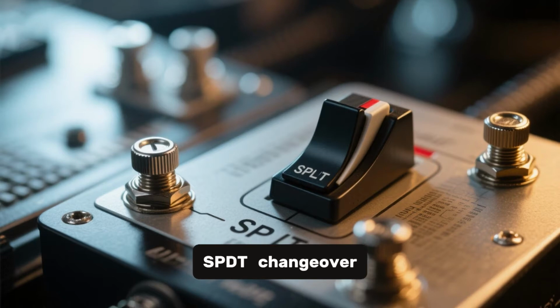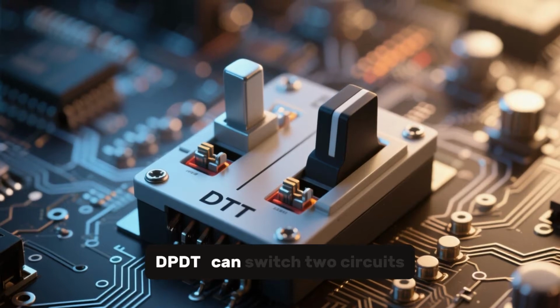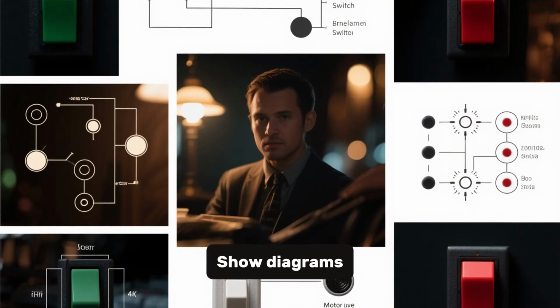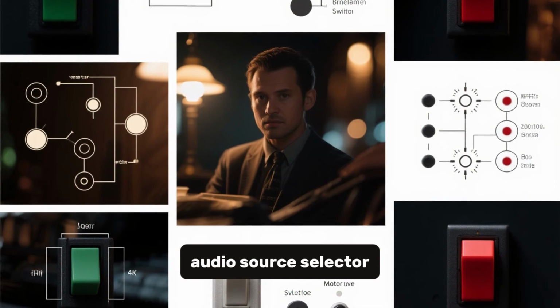SPDT, changeover: one input, two outputs, useful for toggling between circuits. DPDT can switch two circuits or reverse polarity, for example motor direction. Show diagrams: simple wiring examples for each configuration, such as a light, motor reverse, and audio source selector.